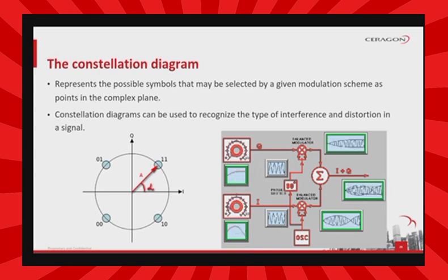I and Q modulation, aka quadrature amplitude modulation, is a method for sending two separate, and uniquely different, channels of information. As you know, the carrier is shifted to create two carriers, sine and cosine versions. The two modulation inputs, analog or digital, are applied to two separate balanced modulators, BM, each of which is supplied with the sine or cosine carriers. That is, modulator number 1 is supplied with the sine carrier and modulator number 2 is supplied with the cosine carrier. The outputs of both modulators are algebraically summed, the result of which is now a single signal to be transmitted, containing the I and Q information.